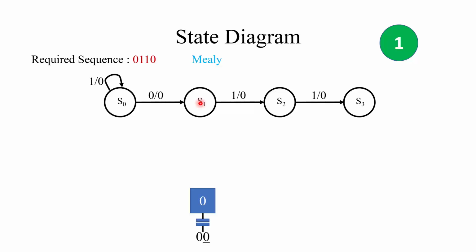Now at S1 we have got two options. We have already covered the option in which we can transition to the next state. Now we are in the otherwise case, when the x input becomes 0, low. We have only two options: either we can stay on S1 or we can transition back to the reset state. In order to figure that out, we follow this process. We take the last bit and compare it with state S1.